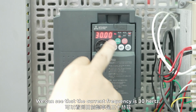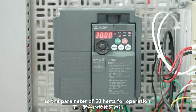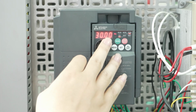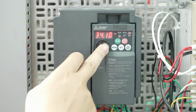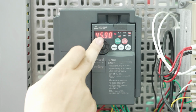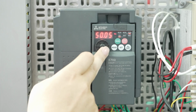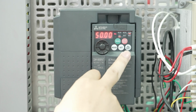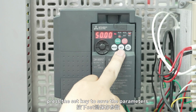We can see that the current frequency is 30 Hz, and we need to switch it to the parameter of 50 Hz for operation. Then we can adjust the parameter magnitude through the knob. Turn the knob clockwise to set the frequency to 50 Hz. Okay, now the frequency has been set to 50 Hz. After the setting is completed, press the set key to save the parameters.